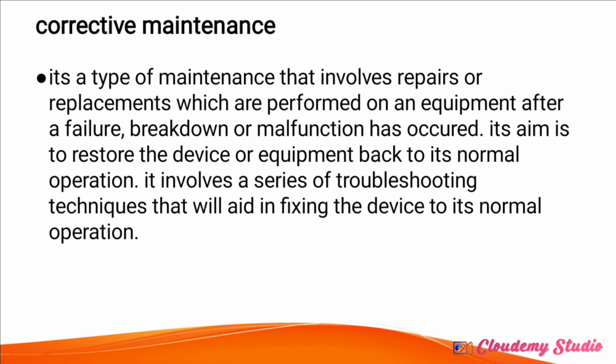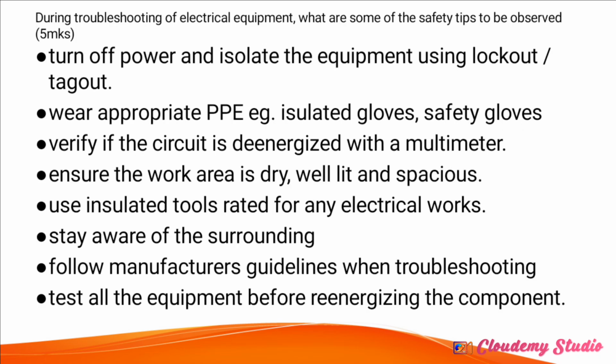So if we come to the next question, which was, during troubleshooting of electrical equipment, what are some of the safety tips to be observed? These are some of the safety tips, and I went through them in class. I said that before you perform any electrical installation, the first thing that you have to do is turn off the power.